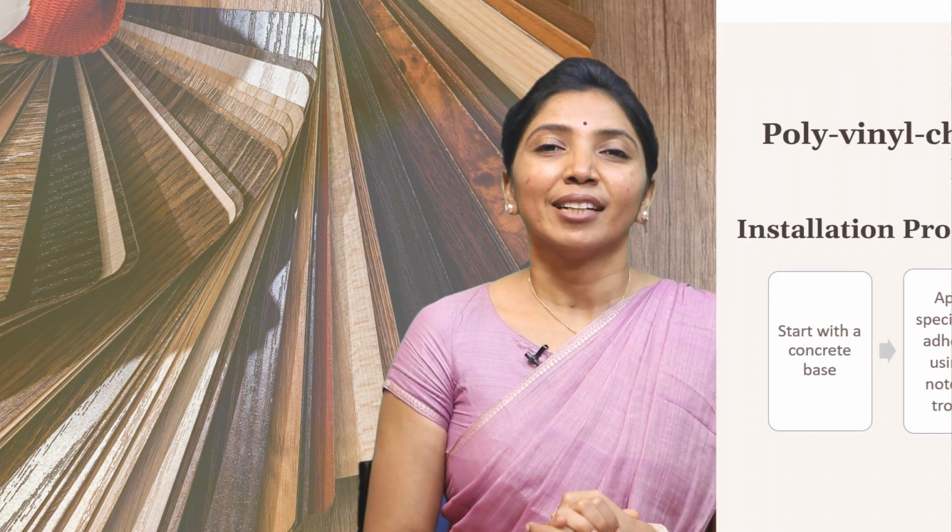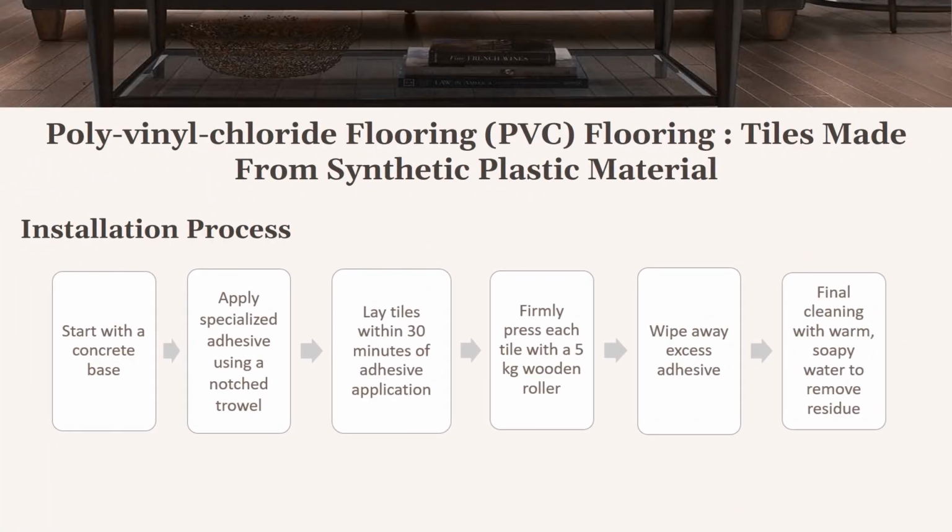Then the PVC flooring, short for polyvinyl chloride flooring, consists of tiles made from synthetic plastic material. These tiles are manufactured in various sizes and color shades, making them versatile for both residential and commercial applications. The installation process begins with a concrete base onto which a specialized adhesive is applied using a notched trowel. Ideally, tiles should be laid within 30 minutes of adhesive application.